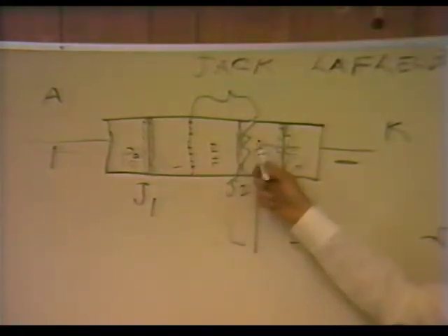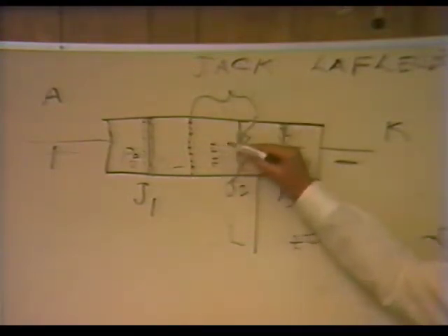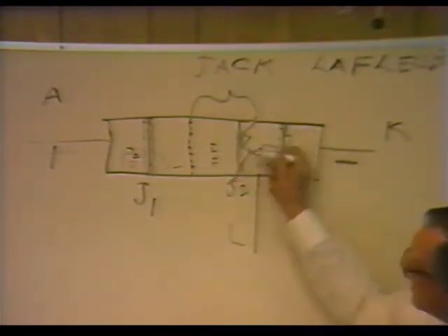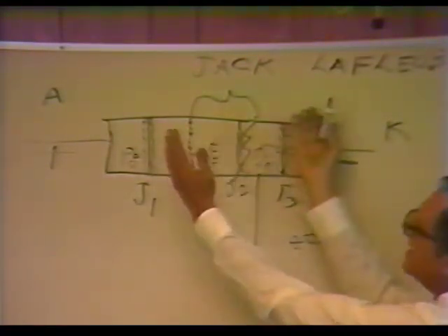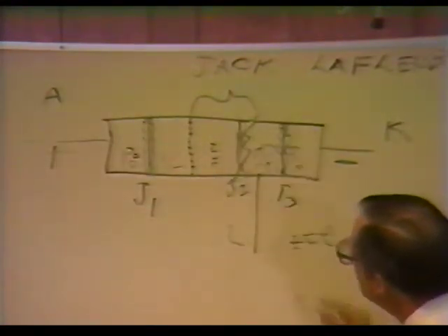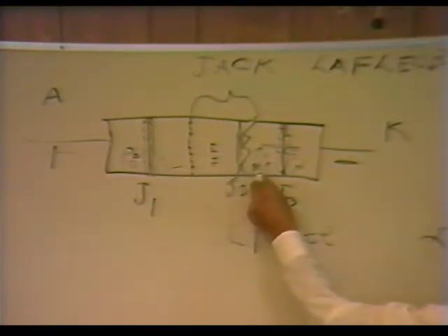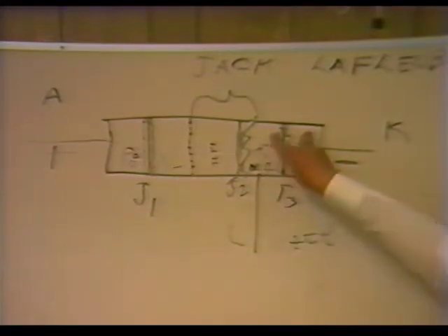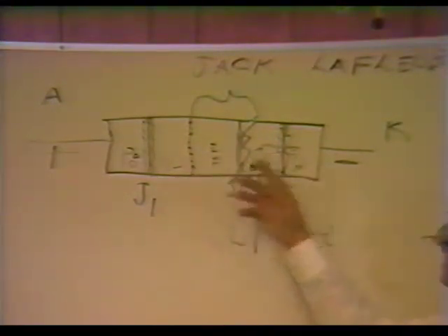Now, what has that done? We have now changed the equilibrium of the blocking junction. We have put carriers in from the N region, we have put holes in from the P region, and this junction now cannot sustain 30 volts, so it drops down some. The P region holes that were collected here are now majority carriers in the P region here. That junction is again unbalanced, and the emitter throws more and more electrons, which do the same thing.